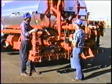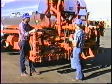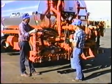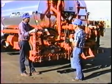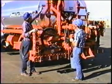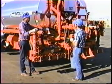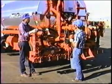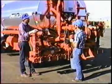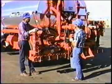In the positive displacement method, the first method where the pump is metering the material, everything we meter goes out on the ground. In that case, we want the relief valve set high. It wants to be well above the actual spray bar pressure, so nothing goes back through the relief valve. When it's on computer, the computer has that set clear up at 50 pounds, way above our actual spread pressure.